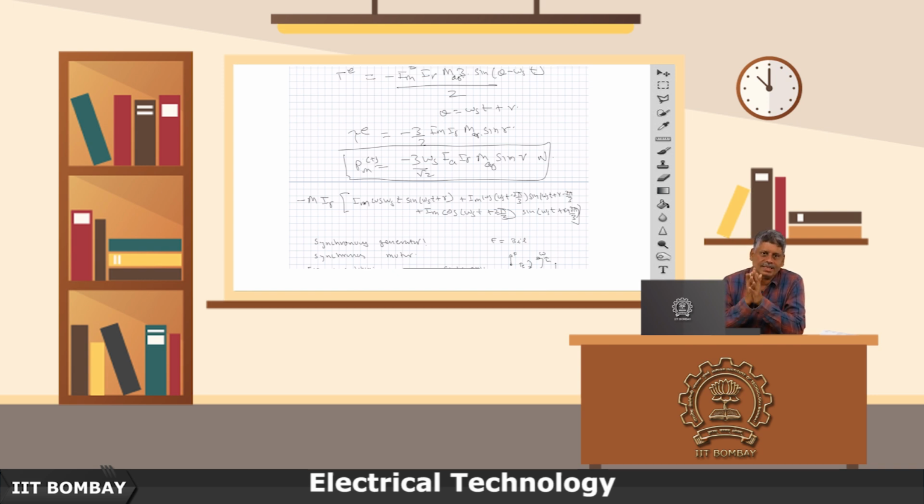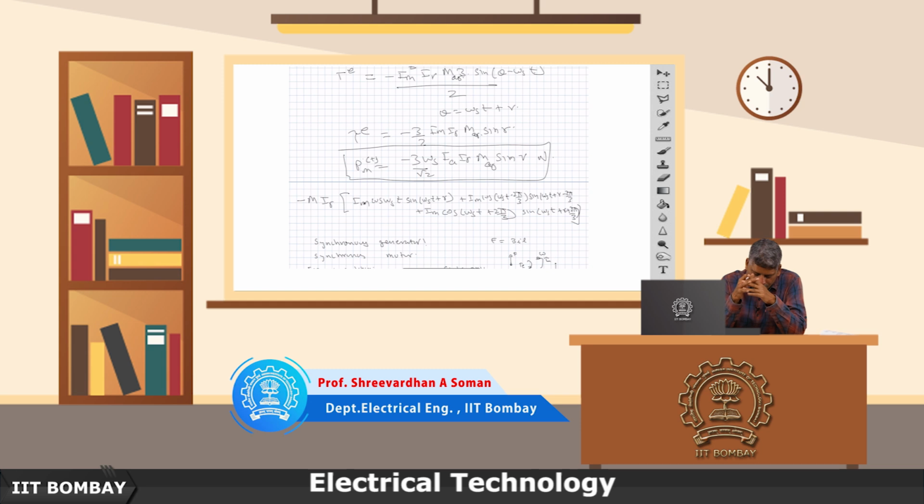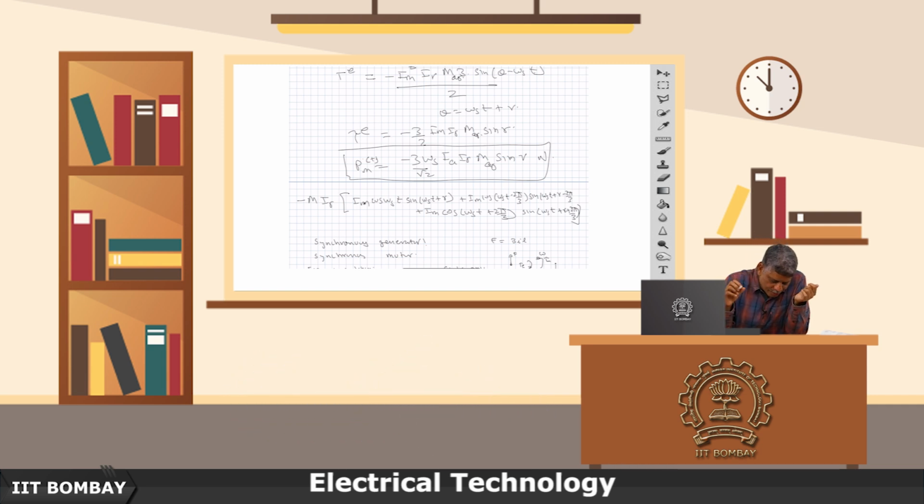Now, we have shown that exactly the same thing with the 3 phase synchronous motor: by having 3 sinusoidally distributed windings in space carrying 3 sinusoidally distributed corresponding currents in time, and the rotor rotating at synchronous speed, I can have a constant electromechanical torque to drive my motor, and therefore, the instantaneous power which is transferred from electrical to mechanical form also will become constant, because the synchronous motor rotates at a synchronous speed. So, we will stop here now. Thank you.